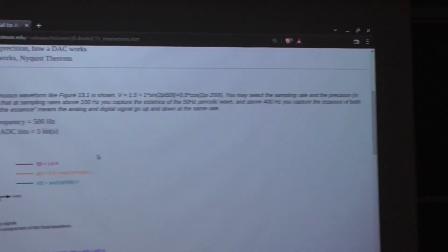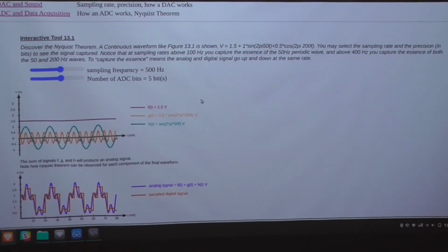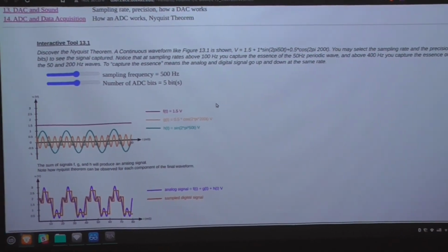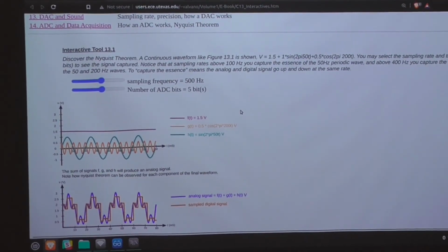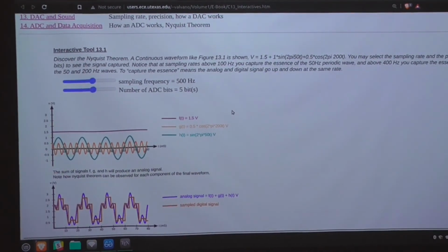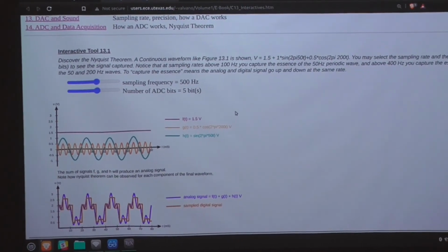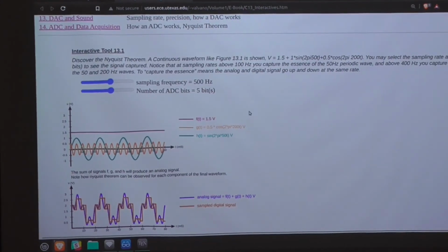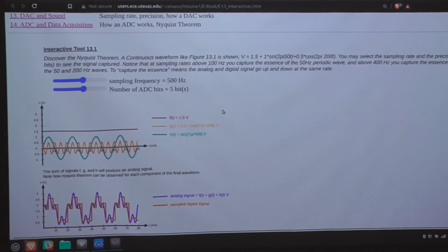The higher the frequency with which you're sampling, the more often you're running the circuitry that performs the analog conversion. And for many applications, you don't actually need to do it that fast in order to meet the requirements of the system. Consider, for example, voice.